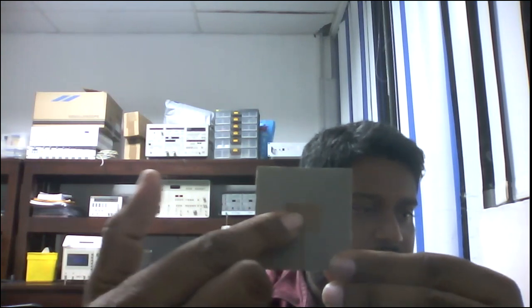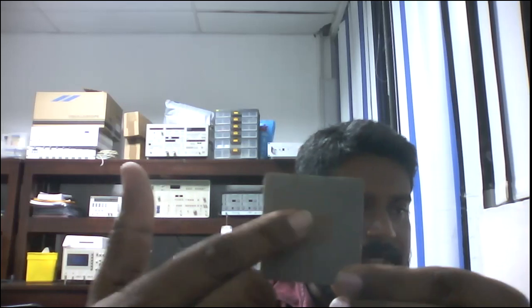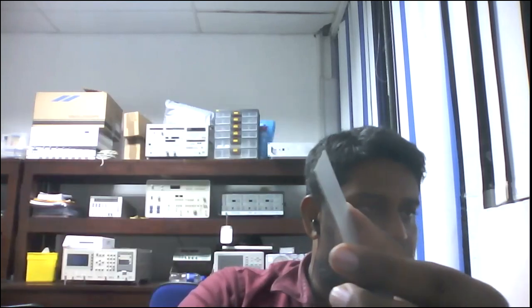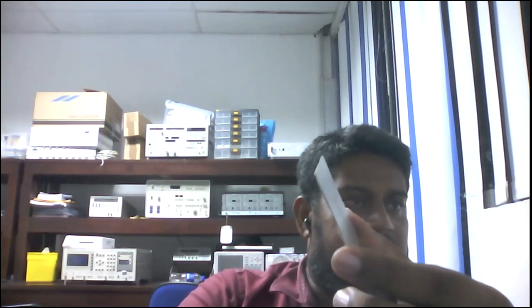So this is a patch antenna, and this is the radiating element. This is a copper plate actually; the copper is painted here. And this ash color one is insulation. This is an insulator. Then again, on this side, we have copper. Actually, this is an FR4 board, which we use to construct microstrip and other structures.